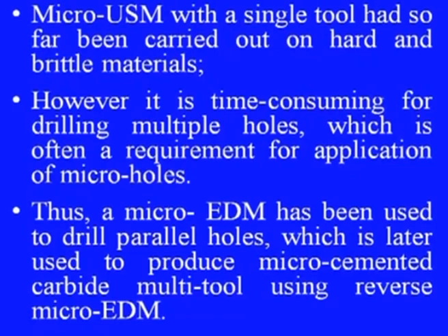Micro USM with a single tool had so far been carried out on hard and brittle materials. This we have already discussed several times. However, it is time consuming for drilling multiple holes, which is often a requirement for application of micro holes. Thus, micro EDM has been used to drill parallel holes, which is later used to produce a micro cemented carbide multi-tool using reverse micro EDM. The multi-tool was further used in mode 2 micro USM.